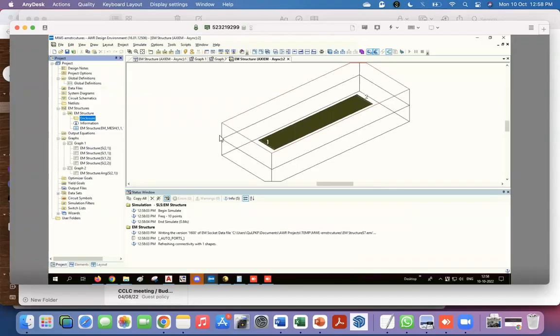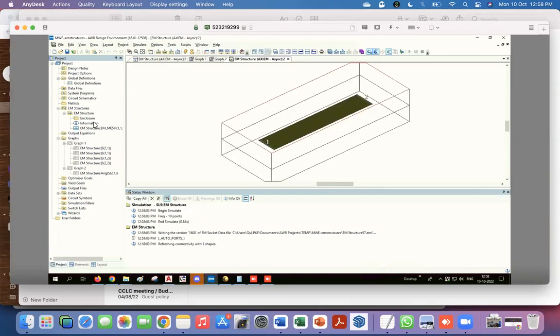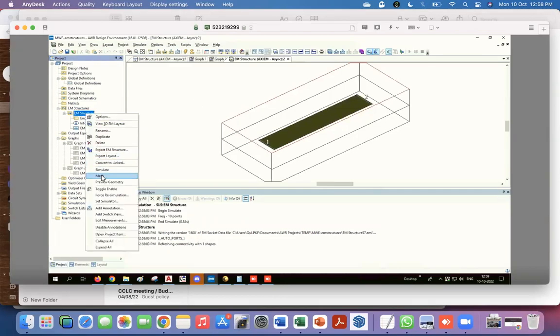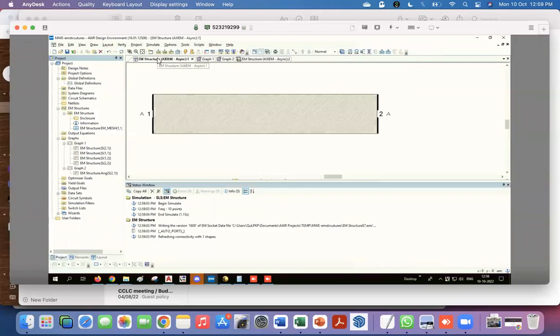So this is the strip line. Now, if you look at the 3D thing, it's the mesh. So you see how the ground reference looks different now. It automatically realized that there are now two grounds. So the port's ground reference is done from both ends. That's why this yellow and the pink things are different. So that's how you make a strip line.